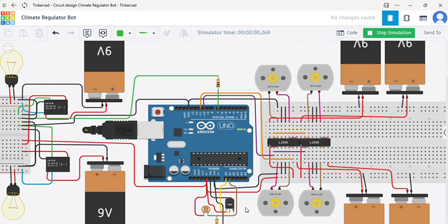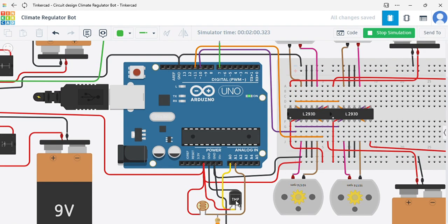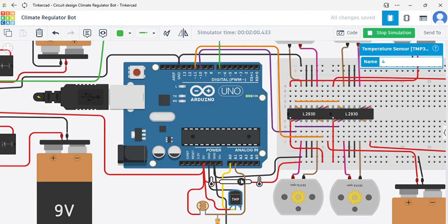The motors are triggered on by the temperature sensor, supposed to be above 29 Celsius. They're supposed to turn on, and below 0 Celsius. Now, we did establish temperatures in Fahrenheit, so I did convert it to Fahrenheit. So in the code, it's going to be below 32 and above 85, but in Celsius, since this temperature sensor is in Celsius, it's below 0 and above 29. So above 29 here, the motors are on, but if you go between 0 and 29, they turn off, and then if you go below 0, they turn back on again.